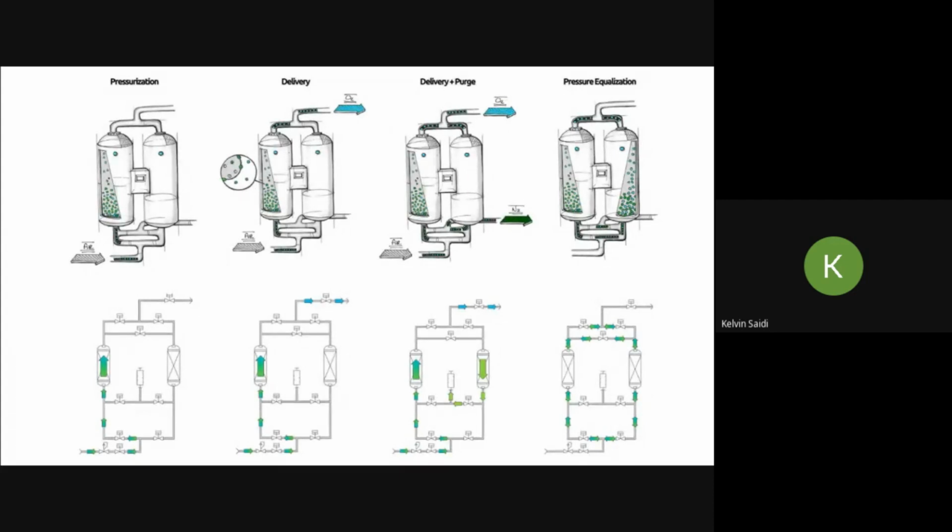The zeolite then adsorbs the nitrogen from the air, and this nitrogen is exhausted via the exhaust muffler. The feeding and exhaust cycles of the sieve beds are controlled by valves, such as the solenoid valve and rotary valve, just to mention a few, and this varies depending on the model of oxygen concentrator.